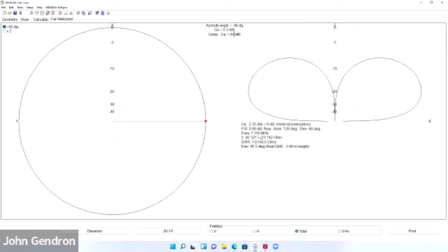Okay. An isotropic radiator is a theoretical antenna. It's infinitely small. It's in free space and radiates in unity gain in all directions at the same rate. Okay. So it's just a comparison. All right. So when you talk about dBi, you were talking about the gain against an isotropic radiator. Okay. A perfect radiator in free space. So you have a little bit better than a radiator in free space.